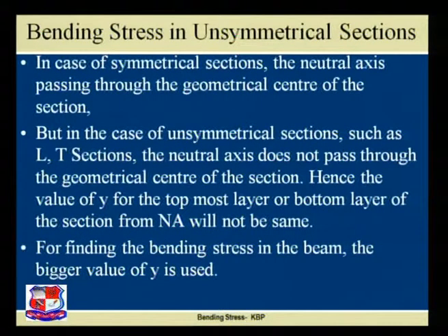Now, we are discussing specifically the bending stress in unsymmetrical section. In case of the symmetrical section, the neutral axis passes through the geometrical center of the section. Please be careful, this statement is very important. Let us understand the statement on this tabletop.